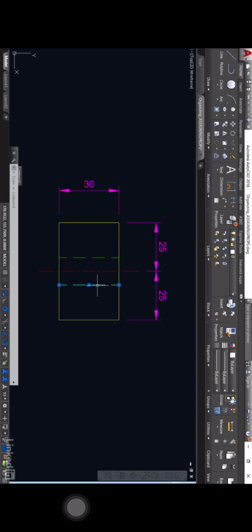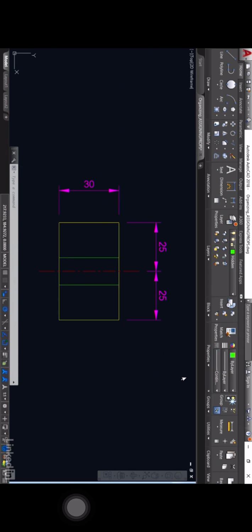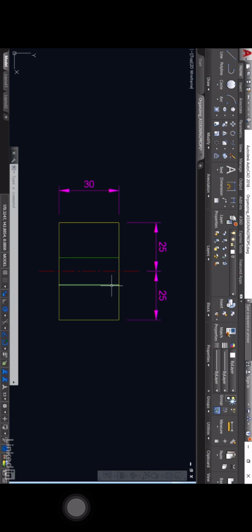The hidden detail, for example, here is using a hidden line type and it's by layer. Let's say I change that to continuous, for example, and I hit escape now to deselect. You can see that it's using its own continuous line type, but it's still on the hidden layer. If I go into layer properties, you'll see that the hidden layer here is still using the hidden line type. So because I'm not using the by layer setting and using an individual object setting of continuous, the line type is continuous. So I'll close the layer properties manager and I'll select my two hidden detail lines again. And what I'll do is I'll put them back to by layer and they adopt the appropriate line type again.